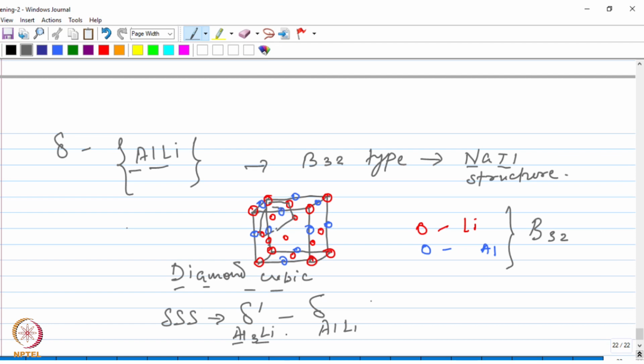order strengthening. But one important thing that you would have seen is the fact that these kinds of precipitates can be sheared by dislocations, giving rise to a low ductility and fracture toughness. So that is the important thing to note here about these precipitates. And as I said, that is what has actually rendered these alloys unusable in many applications. What people thought could be potential areas for these alloys.